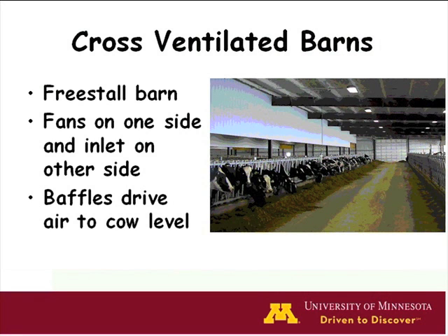Cross-ventilated barns are laid out a little differently. These are totally mechanically ventilated barns. They may have as many as 6, 8, 10 or more rows of free stalls and multiple feed alleys in there, and air enters from one side to the other. In this picture, the air would come in on the right and flow towards the left where the fans are.